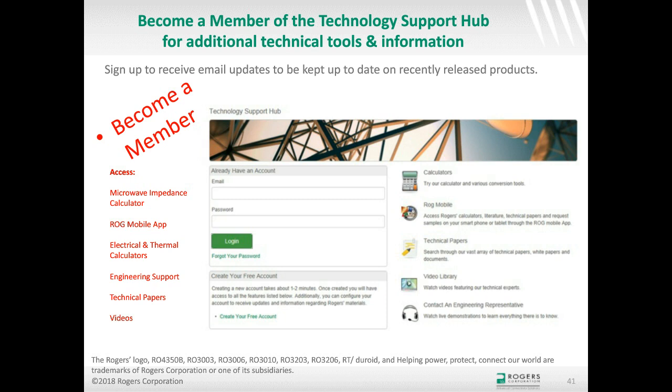And also, color matters, believe it or not. The pigment that's used to color the solder mask actually has an effect on, I think it's really the ionics within the solder mask, and it has an effect on losses. As I remember right, blue, believe it or not, is a little bit better than the other colors. That's all very small numbers, to be honest. But for trying to minimize the effects of solder mask, there's no good way to do that that I know of, except for these little changes I just talked about.